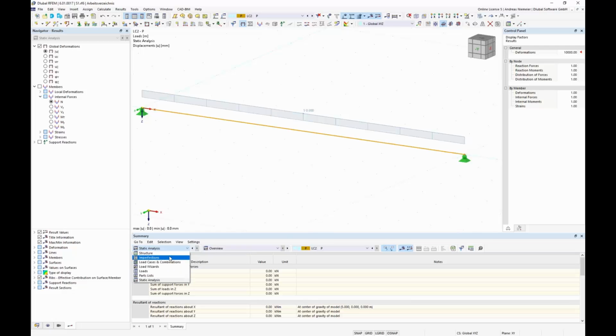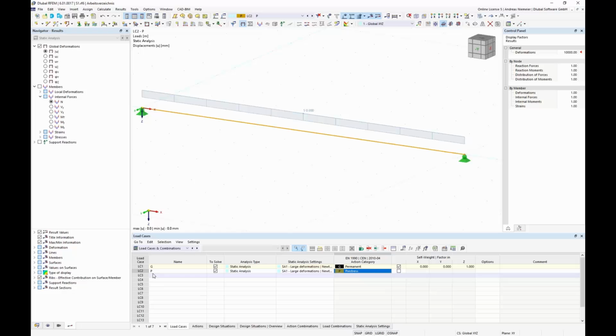In this case, for example, if I take a look at the load case list, we can say, please find me the shape with 20 centimeters for the self-weight, for example. It could be any other load also. But if I say for this load, I have to go to the load combinations and define it.